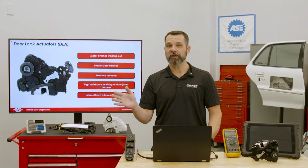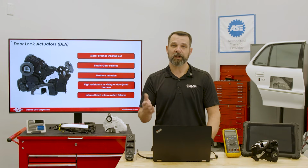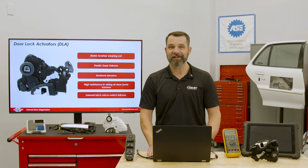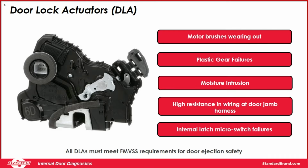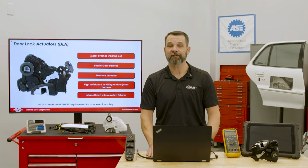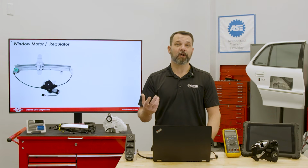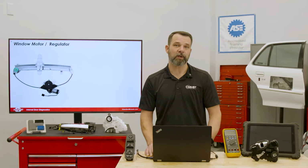Many of these newer modern vehicles will now log lock motor circuit high and low codes, right? And one last thing to note here on DLAs, they all must meet Federal Motor Vehicle Safety Standard requirements for door ejection safety. So if you are replacing one of these, you want to make absolutely sure that they meet those FMVSS requirements.